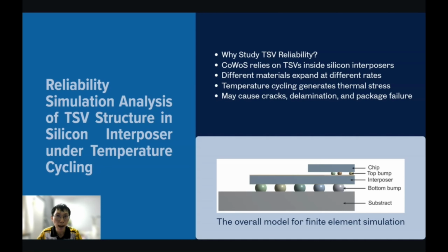Hi, my name is Tang Hongyi, and I'm going to do a literature review regarding the reliability simulation analysis of the TSV structures in silicon interposer under temperature cycling. CoWoS technology uses silicon interposer, which contains through-silicon vias or TSVs to connect multiple chips together.